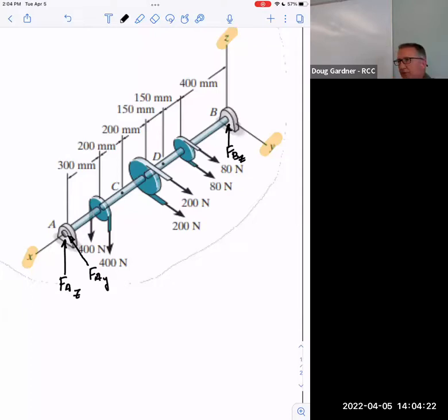And then I looked at the way it was routed over it, and it was exactly this. There was pulling down in two different places. And so that's actually 800. It's only 400 in the cable, but because it's pulling down both, it's actually 800. And notice there's literally two arrows aiming down at 800. And clearly force of AZ, force of BZ are going to defeat that.